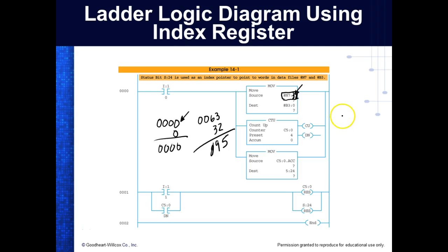So the bit shift that we were looking at, bit shift left and bit shift right, used index addressing. Because what would happen is once it shifted over an entire word, so I could set up a 64-bit shift, well, it would increment the index register, and once it did 16 bits, it would automatically go to the next address, and the next address, and the next address. And it did this automatically by incrementing the index register each time through.